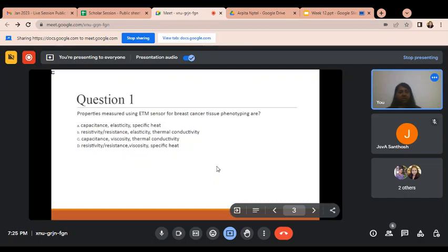We have to maintain the atmosphere, the pressure, and the temperature, or room temperature if we want to do it at room temperature. The main thing is the pressure, and we flow argon. When the argon flows, it bombards the target, and particles from the target come out and are deposited on the surface. This is the sputtering system.